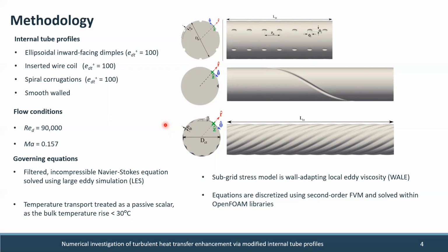The subgrid stress model is wall adapting local eddy viscosity, or WALE, and the equations are discretized using second order finite volume method, and they are solved within OpenFOAM libraries.